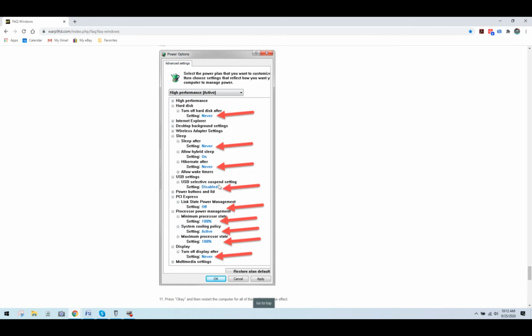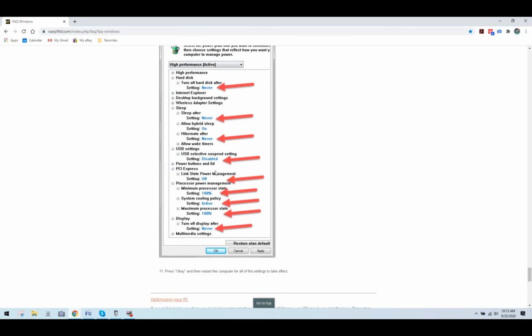Now for my guys out there using a UC100 or a USB Ethernet SmoothStepper, or excuse me, a USB SmoothStepper, this is a setting that you would want disabled, because again, if you have a suspend feature enabled, it can lose communication. So once again, it gives you that false positive of potentially having EMI issues when you're not. So these settings, like I said, going through this video will save you a lot of time and will maximize the performance of your PC so that she can handle everything you're throwing at her for CNC control.